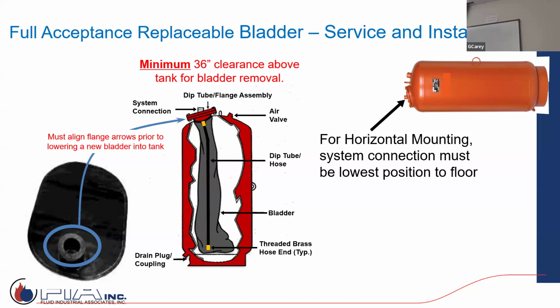And that's another point. I'll repeat myself probably 3 more times tonight, I apologize, but one of the things is when you go from this style to that old steel tank that had air and water and they saw each other. So right on startup, before you turn the boiler on, there was already water in that tank. And that was just because there was no bladder. There's no butyl diaphragm to play with. So that was just how they designed it.